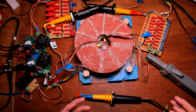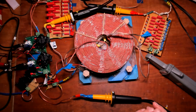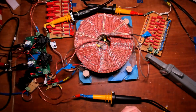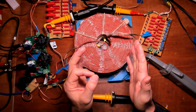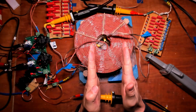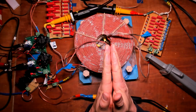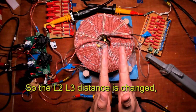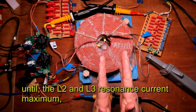I always probe the same way, pointing inwards to the inside rim of the coil. I've done several tests to see what the current polarity is on all the coils, and I learned from that the phase only shifts when L1 and L2 have opposing magnetic fields. So the phase of L2 is shifted by the opposing magnetic field of L1, and when they're really close, it's 180 degrees shifted, but when they're a little bit farther apart, it's 90 degrees shifted. So I can tune the impulse to the voltage minimum where the current is maximum.